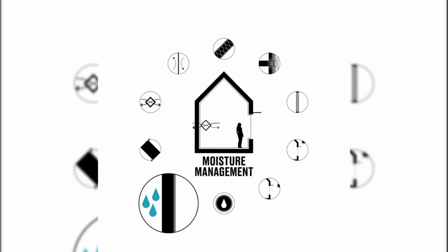Key components involved in moisture management. Weather resistive barrier, WRB, which stops rain and external moisture. Air barrier prevents moist air from leaking into assemblies. Vapor control layers regulate diffusion of water vapor. Structure and openings, framing, sheathing, and windows must be detailed for drainage and drying.